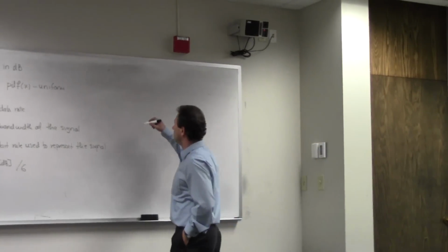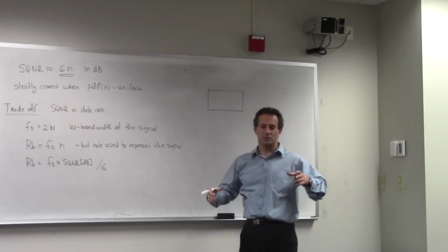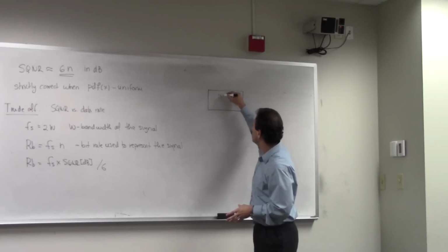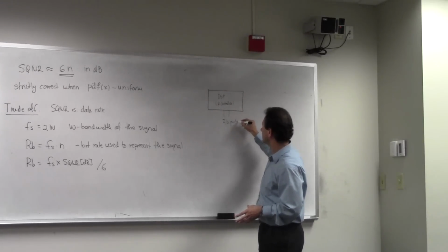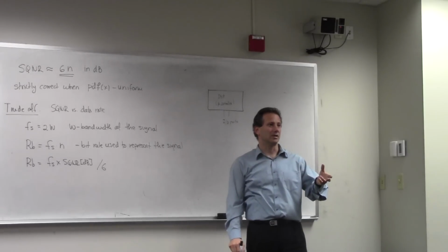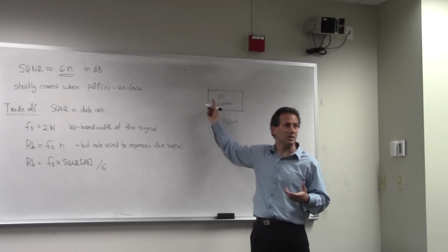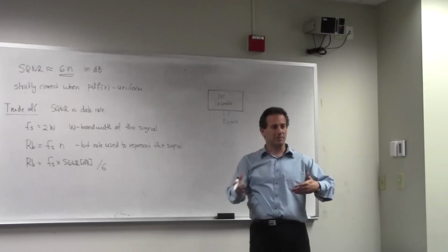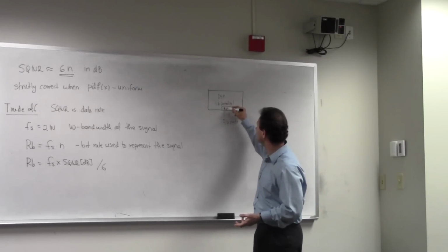Most of the time, our electronics usually come with some signal processing boards. On a board, we usually have a DSP of some sort, or in a simple board, a microcontroller. And microcontrollers have something called I/O ports. These I/O ports are usually followed by the quantizer, right? Because the arithmetic logic units and everything that calculates in here does not know how to handle analog signals. Simply doesn't, because it's doing multiplication of bits and complementing and all that stuff. So there is an analog to digital conversion that happens at these ports.